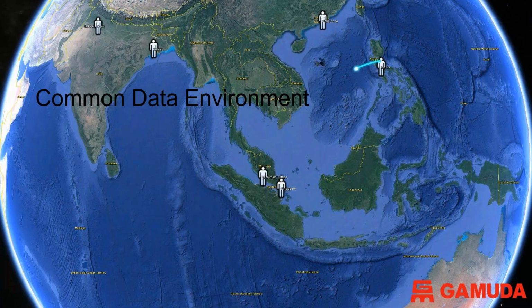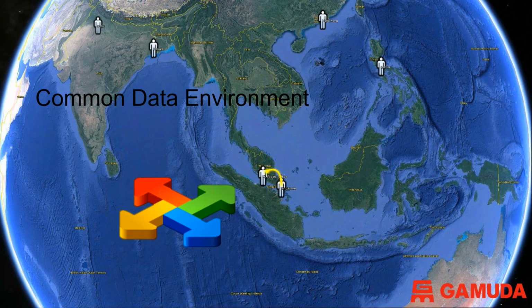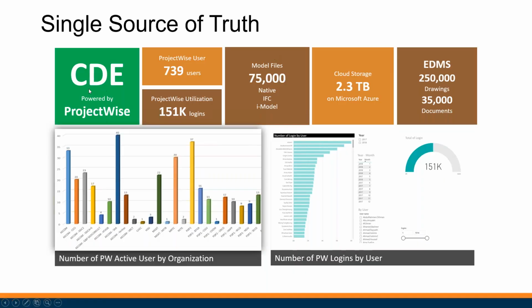Now, the backbone to all of this, and I mentioned this earlier on, is the common data environment. So on this particular project, we're using ProjectWise. We have staff in Kuala Lumpur, we have staff in Singapore, we have staff in Hong Kong, we have staff in the Philippines, and we have staff in India. While we have co-located engineers leading the design, all of their supporting teams that were doing the engineering calculations, a lot of the modeling work, a lot of the drawing production, a lot of the design management, they were being done offshore. So we needed a platform that we could link all these locations together. So this common data environment, or CDE, which is another common BIM term, we use ProjectWise.